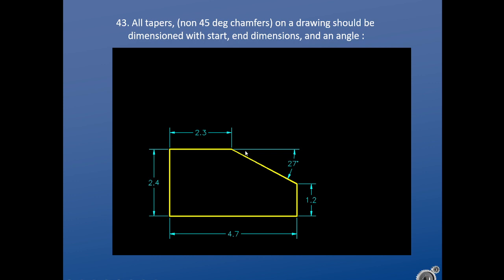And this is a decision based on what is important. Is this length important and this angle? Or is this length important and that relative angle? The way we've done this, I would say the 2.3 and the 27 degrees are the important aspects to me, the designer, because that's how we've made the angle is the 27. And the 1.2 is probably less important. I could delete that.